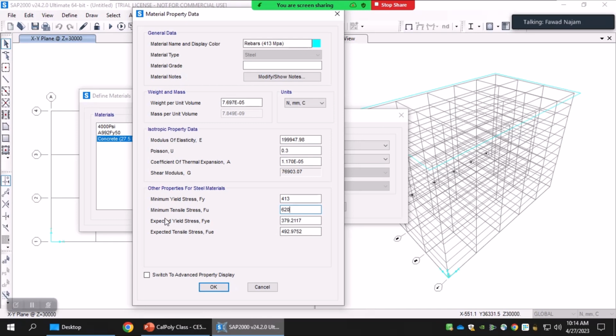Right. So again, the expected yield strength is higher. There are different standards which guide us on how much higher the expected value should be for steel compared to the nominal value. Generally, it is assumed that the expected value is 15 to 20% higher than the yield value. But since we are using this model only for the purpose of structural analysis and not for structural design, no matter what value we give, it will not be used for analysis here.